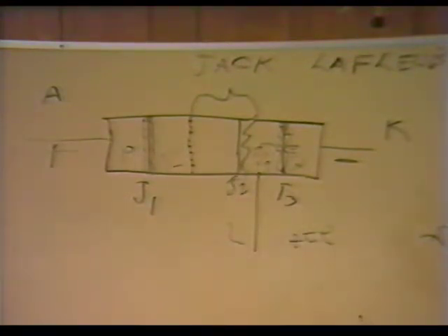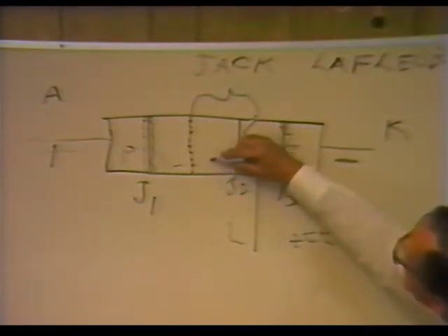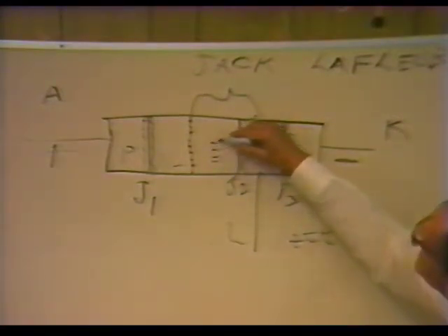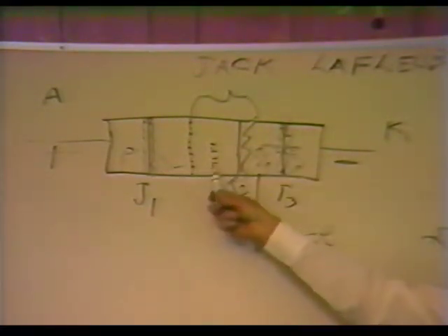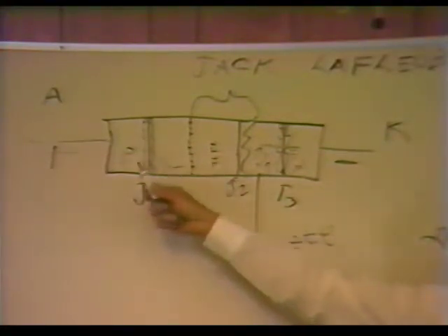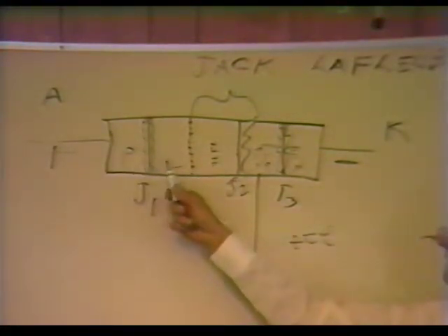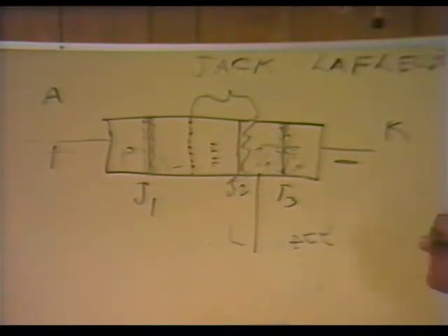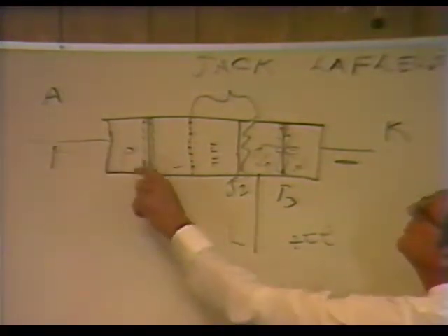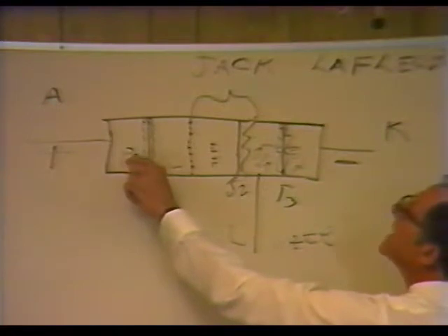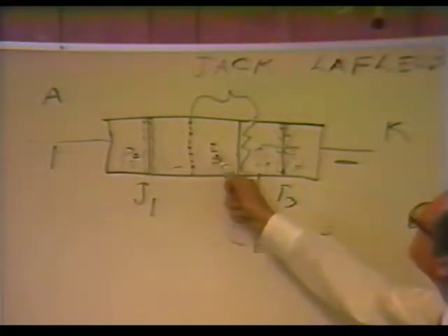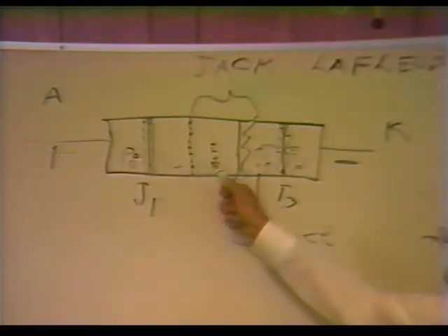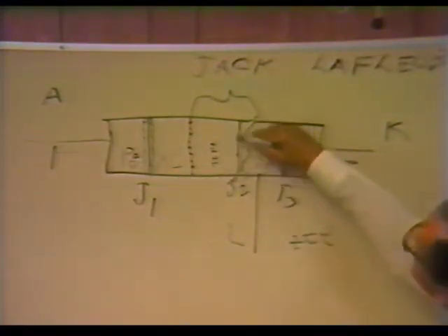Now what does that do? Now we have these electrons that came across here, and they are now in the N region where they are minority carriers. Now we have more carriers in the N region than we have here in the P region. We have unbalanced this junction. So what does this do? It starts to bring things back in balance, so it starts to emit holes. And the holes go across this N region where they are minority carriers, and they are collected at this junction.